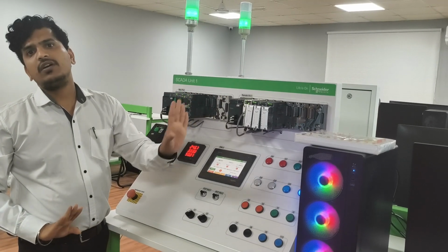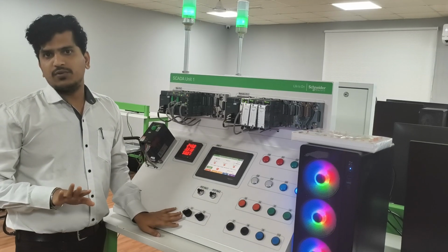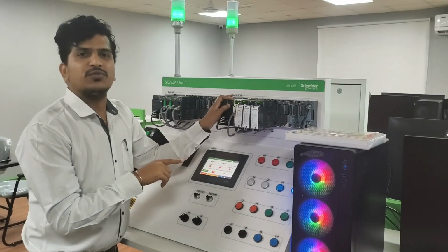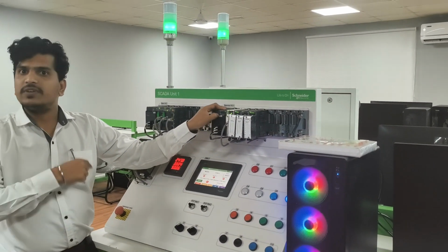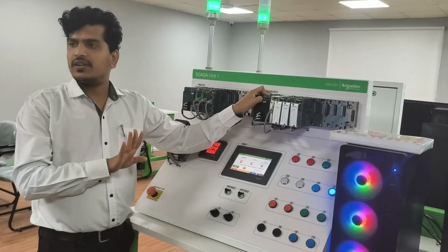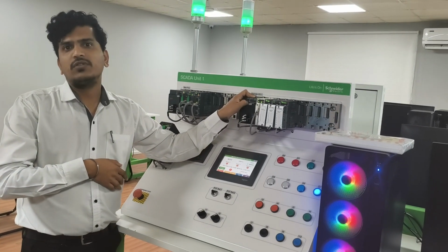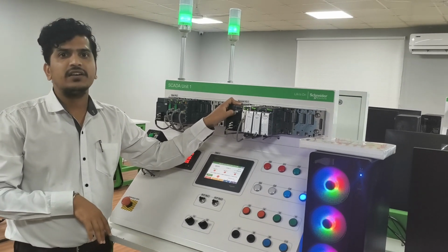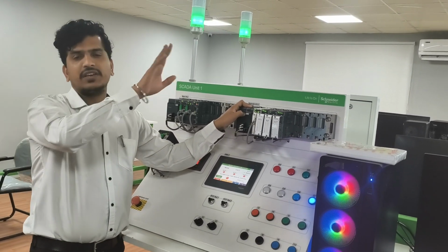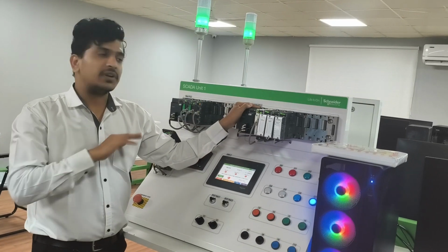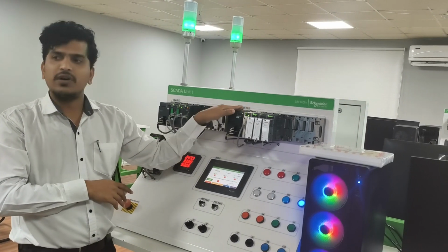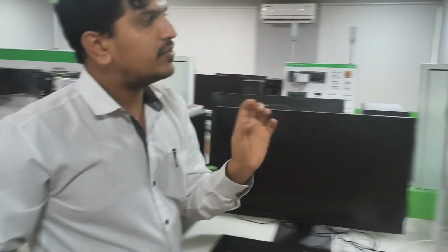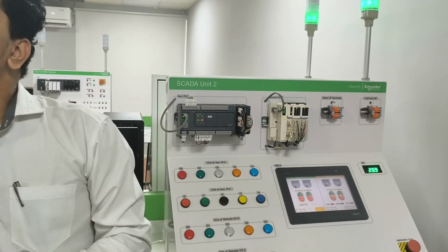This is operating only for pump, valve open, close, and level. For this one, here we are using an IO scanning network. So we will teach not only Scada and all those things. We will teach the communication protocols, how in the industry different communication protocols will be there, and how to integrate with the PLC. So there we can see only one protocol. Here also one protocol. But here, different communication protocols. With the help of IO scanning, we will communicate with this PLC. Next, to communicate with this PLC, we use one more, that is Ethernet IP.